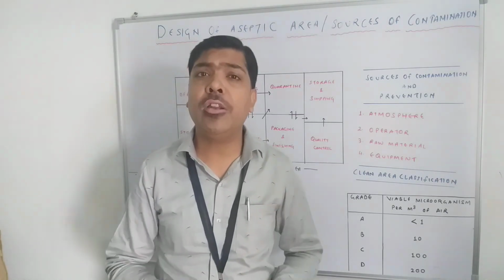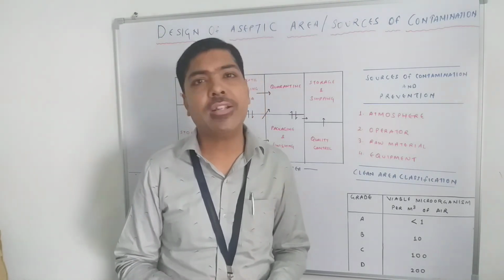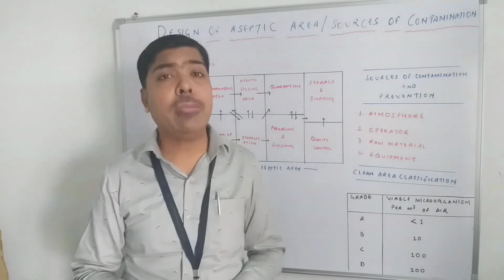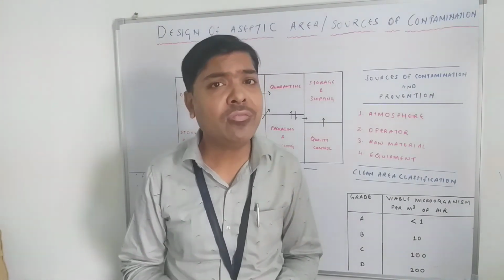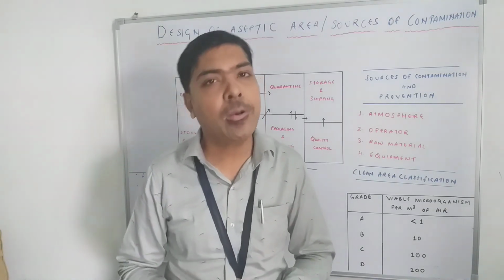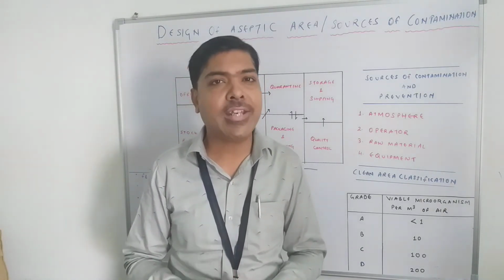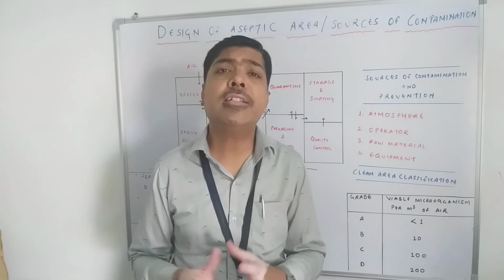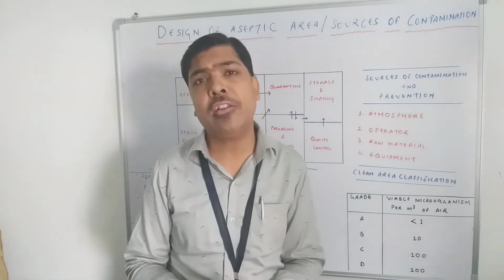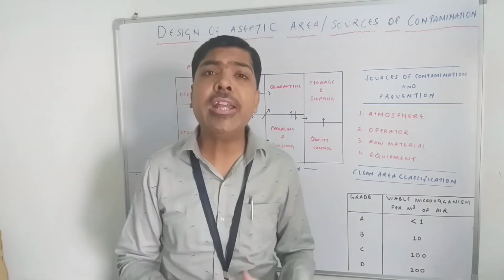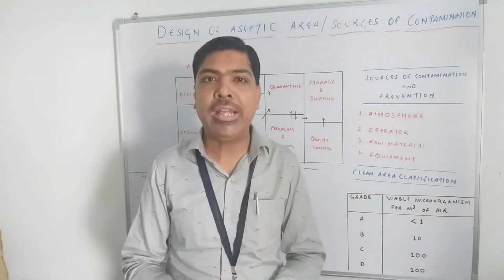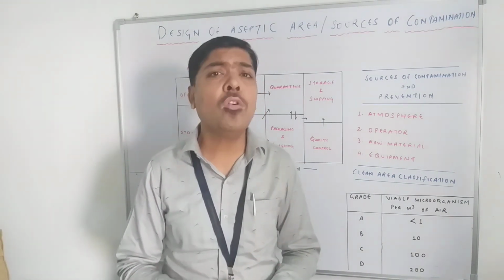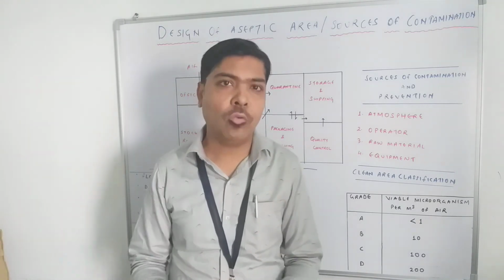Some floors are called flexing floors, made up of a material like polyvinyl chloride, because polyvinyl chloride is very easy to clean and easy to repair. So we can easily go for this type of flexing floor. Some non-flexing floors, which are made up of some inorganic filling substances, are also available in the market. We can also go for concrete floors.